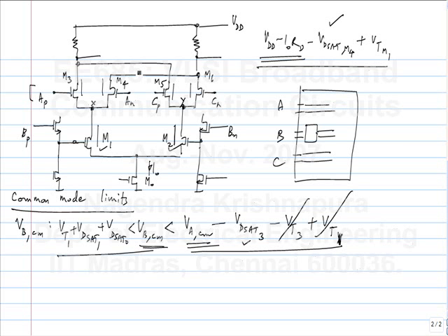What might be the problem? You tell me. Let's just look at this itself, a single gate, and you want to use this as a switch. I say that the transistor should be in saturation. Of course, it's a switch, so one of them will be in cutoff, but the on transistor should be in saturation. What would be the consequence if it's in triode region? Yeah, there can be a larger transition region.